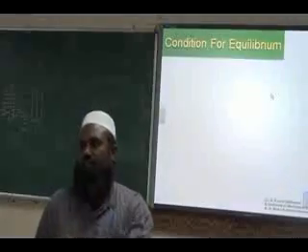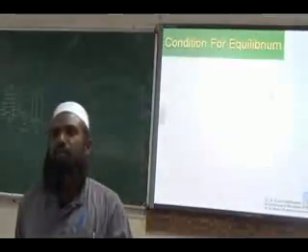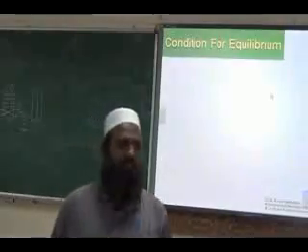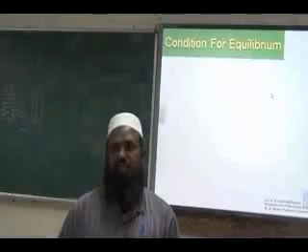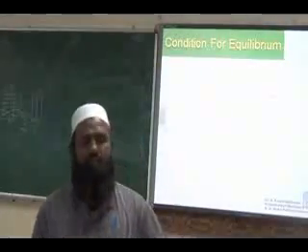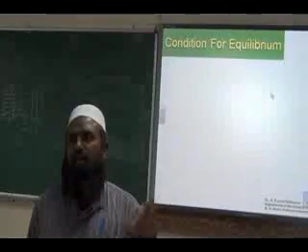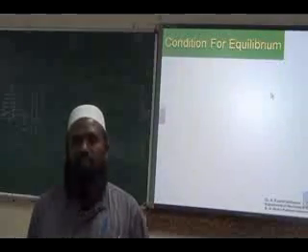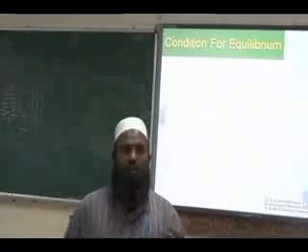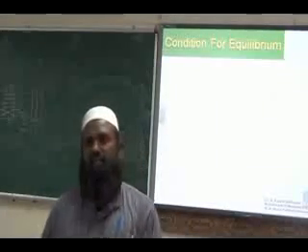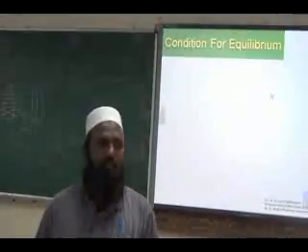We know there are reactions and we have seen what types of reactions we will have for a particular type of constraint. If it is not allowed to move in x direction, we will have a force in x direction. If no movement in y direction, force in y direction, like that. So we have seen different supports and their corresponding reactions, either a force or a moment. Today we will see how to find out the magnitude and direction of the reaction forces and reaction moments.